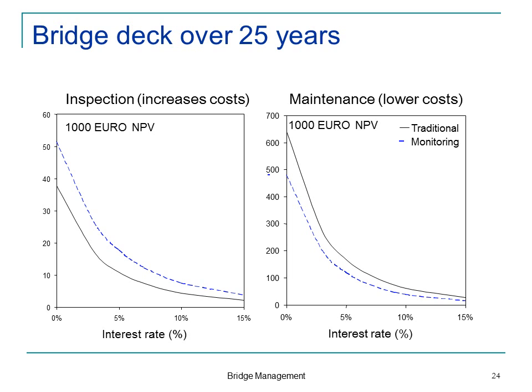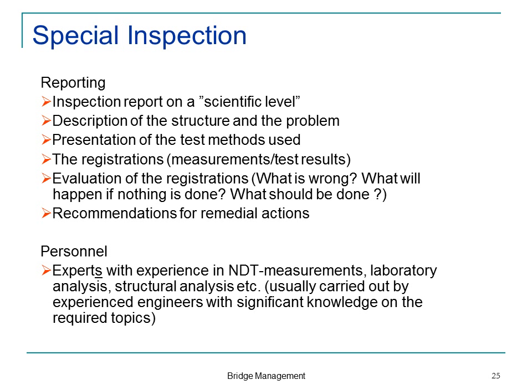It can just be to insert some sensors and have some cables so you can make a measurement without blocking the traffic, and you can make the measurement when you pass by that bridge anyway. What we often see is that it makes the inspection a bit more expensive, but in the long run, it makes the maintenance lower. We spend less money on maintenance.